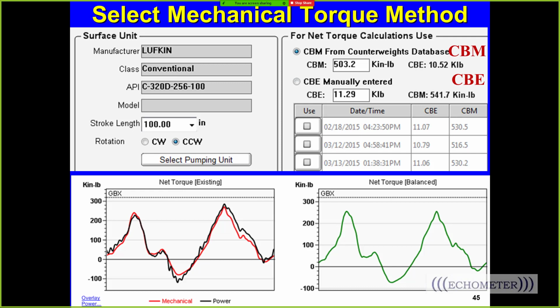Anthony Allison has a comment on the gearbox live plot, and he says, I think Cecil assumed constant operation at a given RPM on the gearbox, but I'm not sure what RPM was used. He also says that there have been some empirical values for the cyclic loading factor published by unit geometry and prime mover type. Have you ever compared these measured cyclic load factor values to see how they compare?